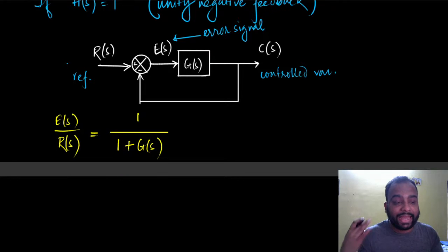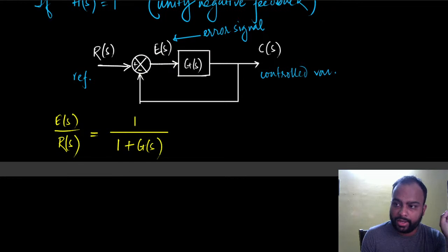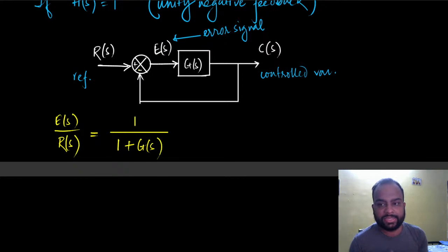And the moment I say enough time has elapsed, I mean steady state. After the system has reached steady state, once I have given it enough time, then I would expect the reference input and the control variable to match. I would want the reference variable and the control output to match, because there is no feedback transfer function here. Essentially the feedback transfer function is 1. So this is something that you have to understand at this moment.